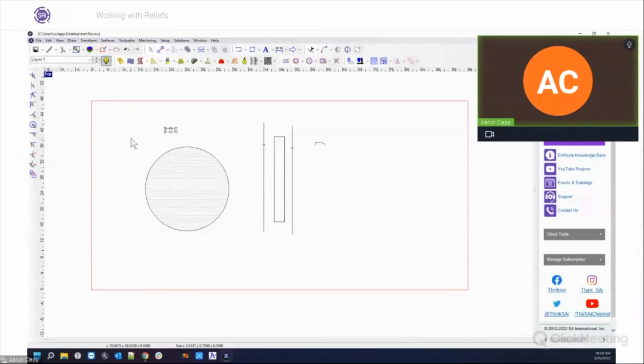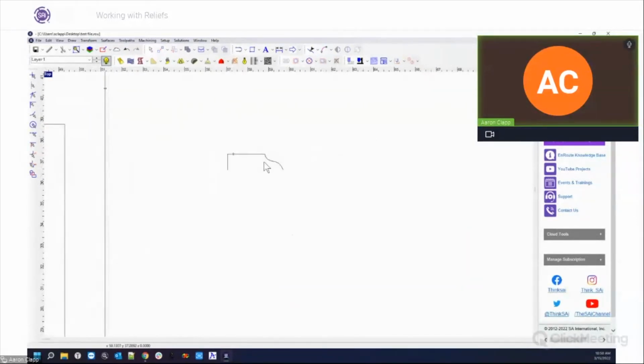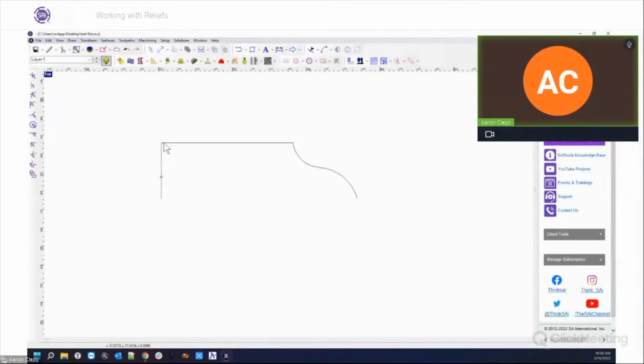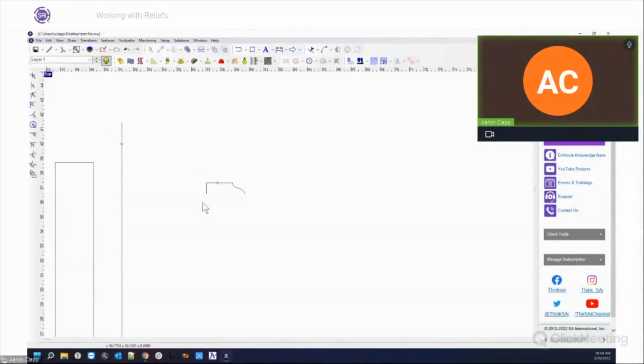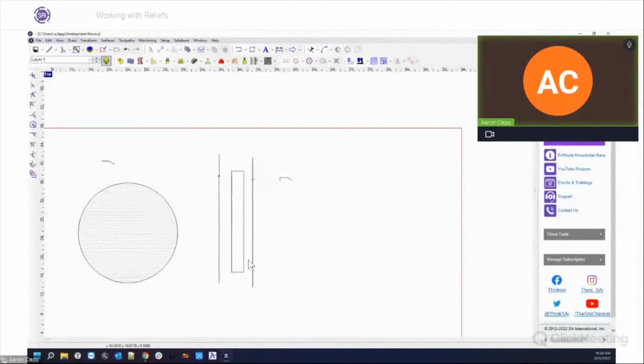Let's look at another example. In this example, I changed the contour just slightly. In this particular case, I added this little backing here. The reason is that with sweep to rails, it usually works a little bit better if you have a flat relief to start with, and then you use your profile to define how tall you want it to be. So I've just added a little bit of a backing to it, and that's basically all I've done there.